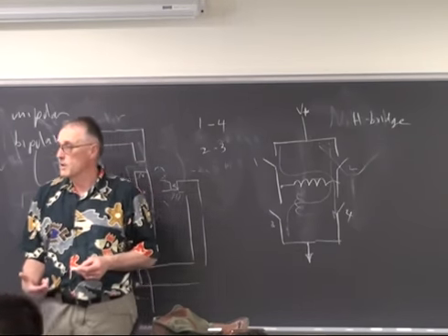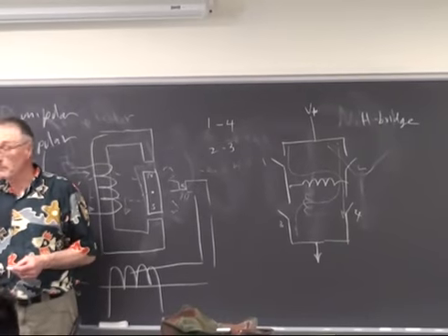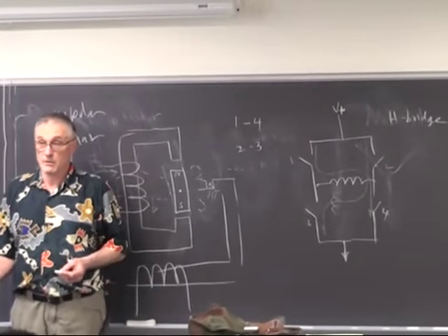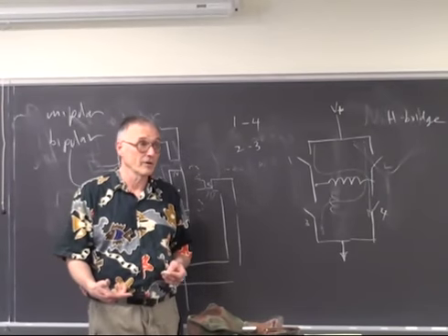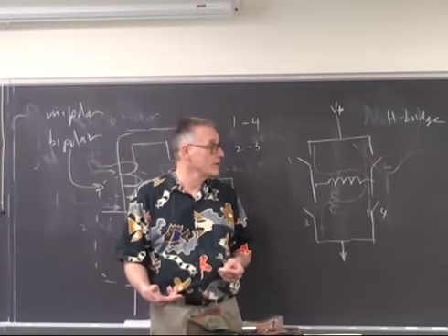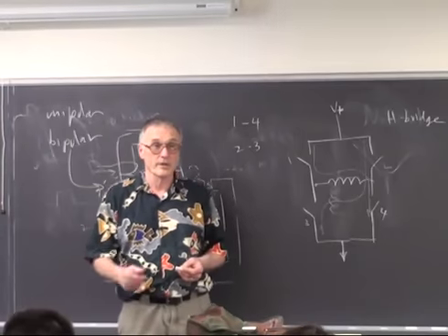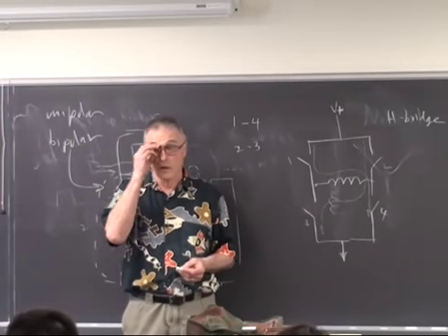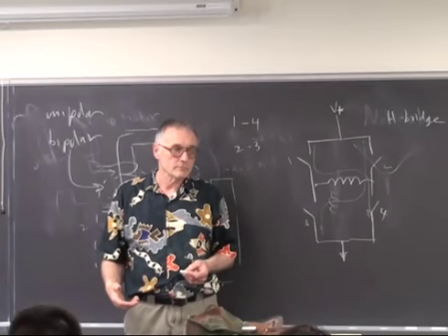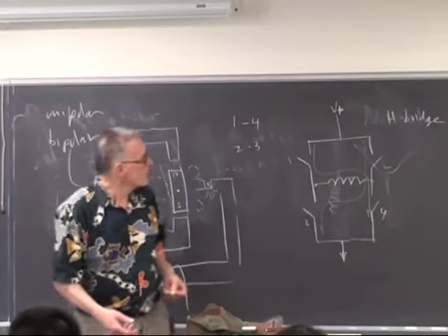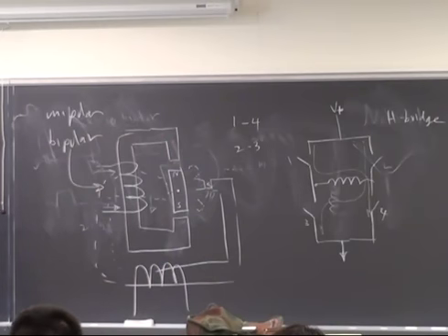Or, a much more reasonable thing to do is you buy the H-bridge. They cost pennies to dollars depending on the current level, but you can buy a 1 amp or 2 amp H-bridge for around $1. Why would you possibly build it? Because you ran out of time. But think ahead. Don't build H-bridges.